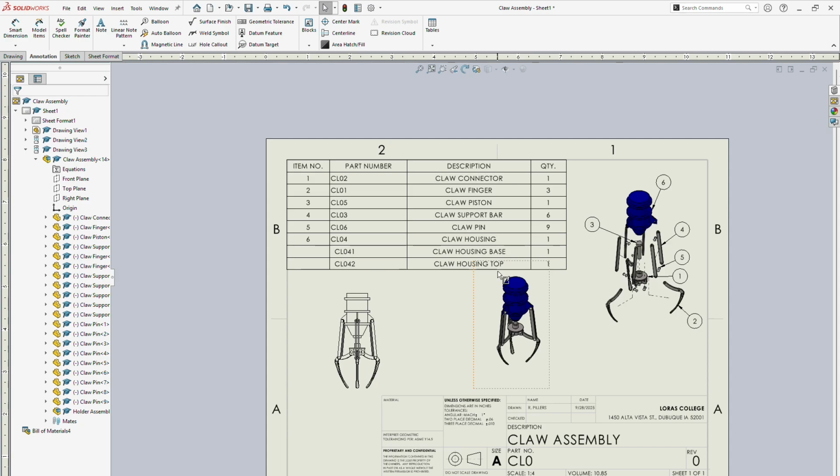And then a couple other pieces while we are on the screen. As far as views, you're normally going to have an exploded view. You're normally going to have an isometric view, because the exploded view shows how things go together. Isometric view shows what it looks like when it comes together. And then you might have one or two of your front view, side view, etc. that you think could be important or could be helpful to see.